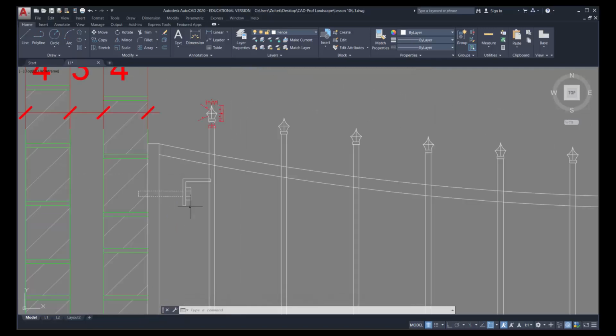So I know that that bracket is 2.5 inches out. I need an intersecting line here so that I can place it properly. So I'll select offset. And in the diagram I show drawing a couple lines. I can actually offset the fence that's right there. So 2.5. And you'll notice that's a rectangle, so it's offsetting in that manner.